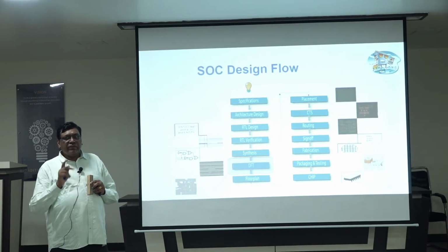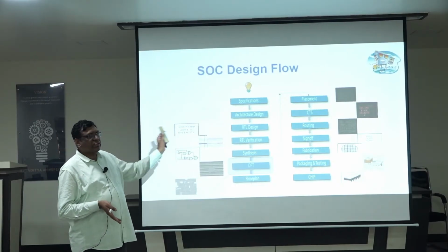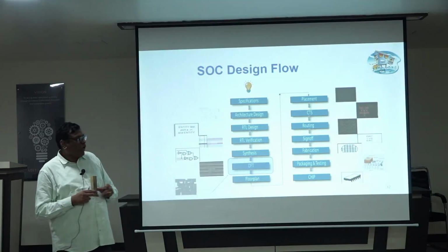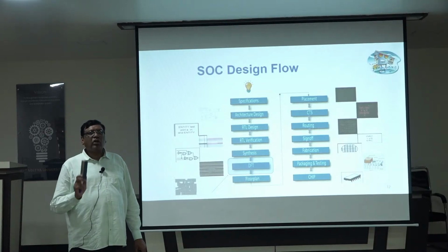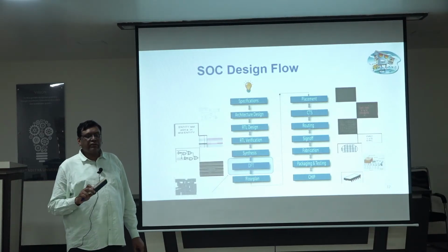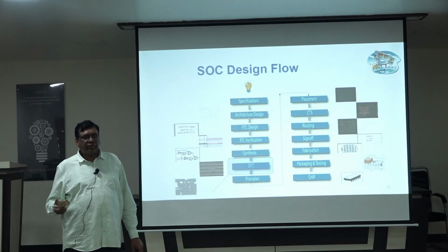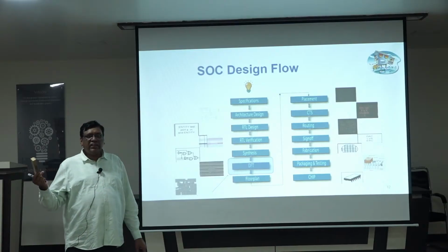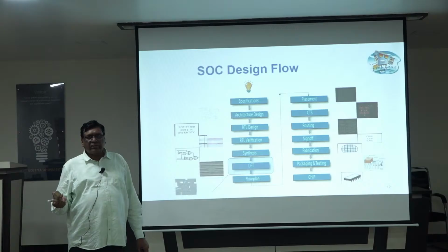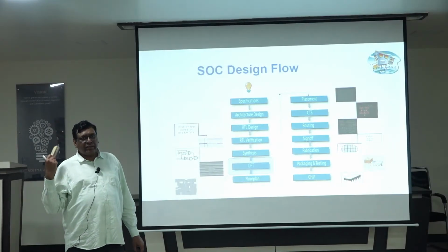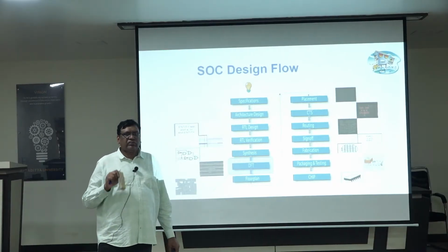The verification we do in RTL verification is different. What you verify in RTL verification is the functionality of the RTL code, not the hardware. There is no hardware yet, so you are not verifying hardware there. You are verifying its functionality. But our intention is manufacturing testing, that means after manufacturing we have to test it. That perspective will be covered by DFT, but this verification will ensure that the circuit design is correct.